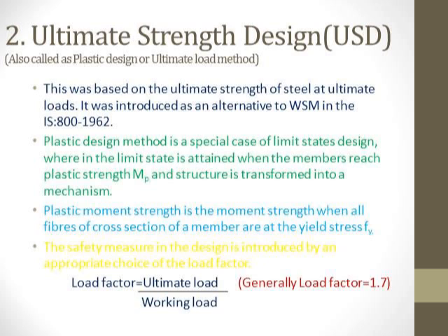The plastic design method is a special case of limit state design, wherein the limit state is attained when the members reach plastic moment strength Mp and the structure is transformed into a mechanism. Plastic moment strength is the moment strength when all the fibers of the cross section of a member are at the yield stress Fy.